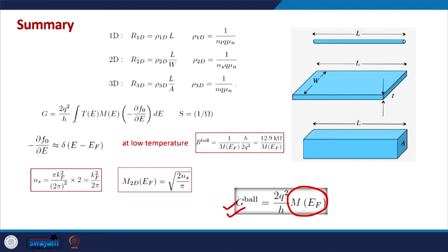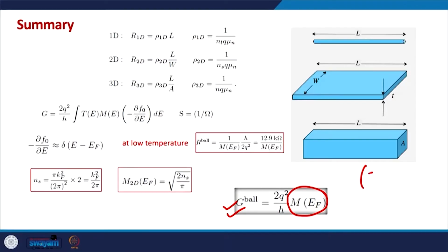value of the conductance. So, all this was true for low temperatures when T approaches 0, which means Fermi function is approximately a unit function and Fermi window is a delta function. In those cases, the calculations are easy. Then we started doing calculation for above 0 temperature cases, at room temperature cases. So at those temperature values, we realized that this Fermi window function can no longer be approximated by a delta function, and in this case